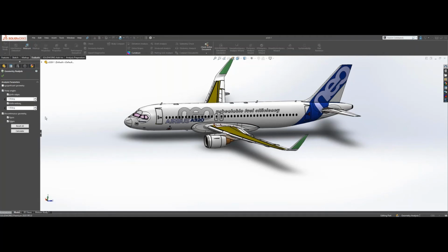If you do some regular simulation, the knife edge is a good point to investigate, because any of those knife edges can result in an undesirably dense mesh. So many different things can happen there. Now you might have to add some mesh control and so on. You can also look for discontinuous faces as well as discontinuous edges here on the left.